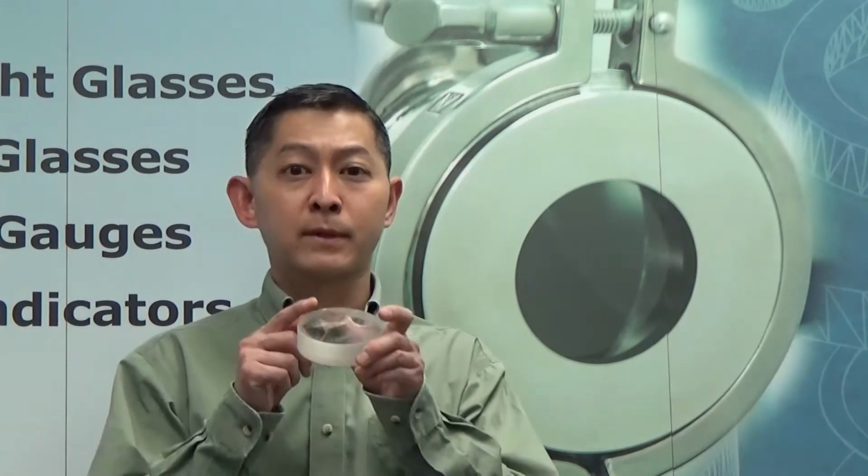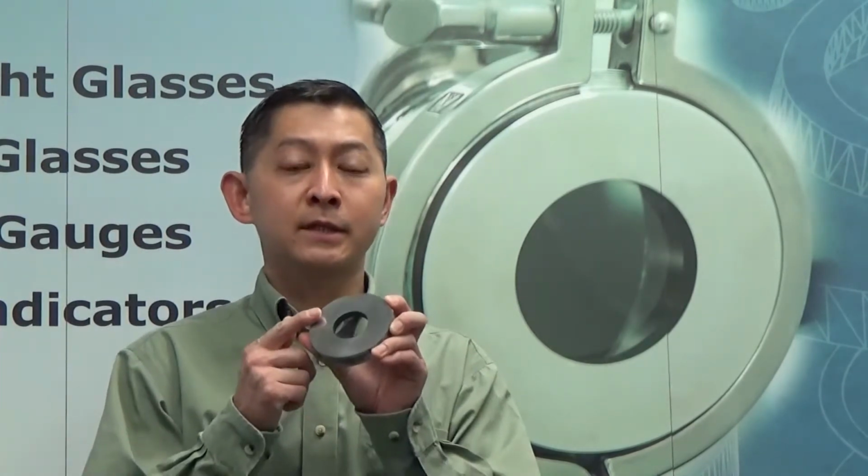In this failure mode, the glass is being crushed by the gaskets, and you'll see radial fractures along the rim of the glass right around here. Now, there are a couple of ways of getting around this failure mode. One is to use a fused glass, and you can see that the metal surrounds the glass, and as the gasket will be on the metal, you can apply stresses on the metal as you like. Now, this is a definite advantage of this type of sight glass.